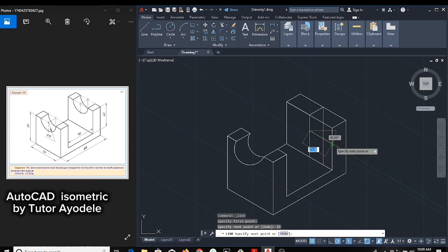You see, all my drawing is in 30 degree. You see that is in 30 degree or 150 degree, that's what it is, or 90 degree. So I enter that. I click on it. I enter it. And if you check this, from this point to this point is 15 already, so I don't need to hold that anymore. So now we can get our circle using these two points, the center and where our circle will extend to. This is the center of the circle, and our circle will extend to this point. So you can see the circle is already given. So we can enter it.